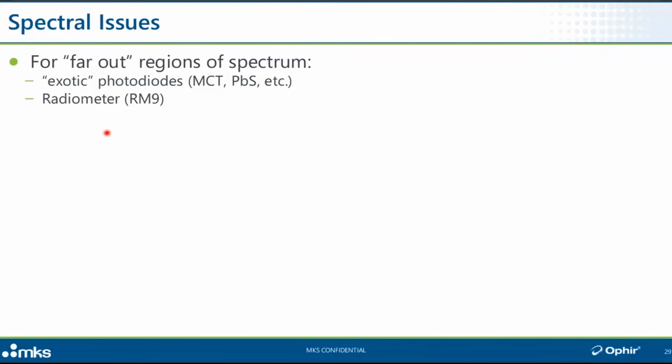modulation frequency. And what we've just done with that, I know in the Ophir instruments that are based on a radiometer, the background is cut down by something like 3 orders of magnitude, and the noise is cut down more or less completely. There's noise and there's offset, there's background. So the background is cut out more or less completely. Sorry, the noise is cut down by about 3 orders of magnitude. Sorry, switch those two around.